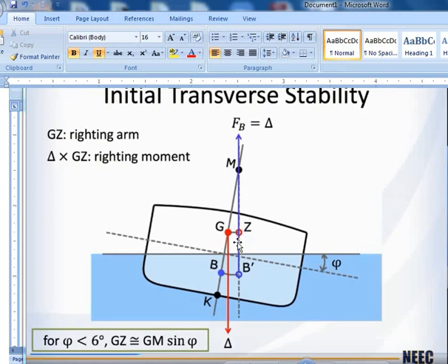You are also supposed to draw something like this to show. Let's consider this diagram very well. You can see when the vessel was upright, the K will never change. Like I said, the B will tend to change because that is the water level. When it was full, the water level was covering this section. Look at the line. But when it was tilted down, the water level is taking this section. You can see there has been an increase here, and that increase will determine whether the ship will come back or not.